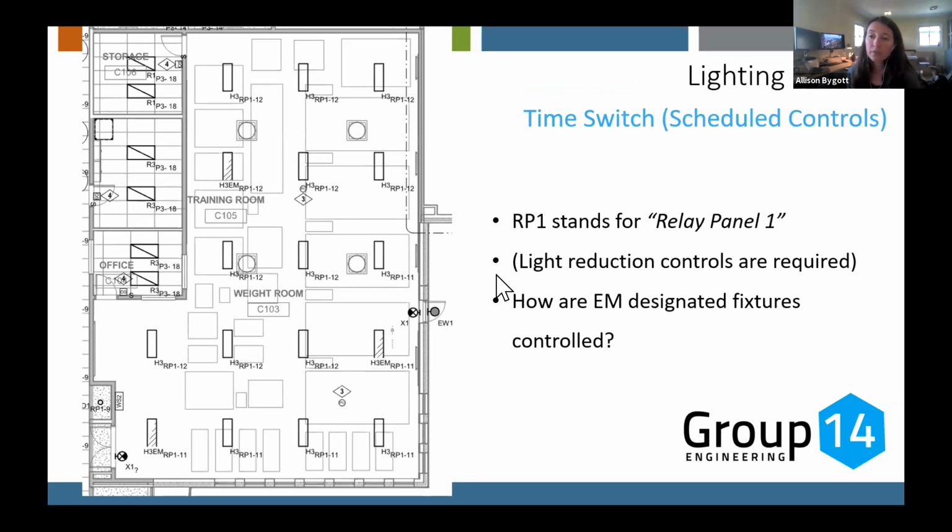One thing I've really bumped into is the IECC functional testing of lighting controls does not ask me to review emergency lighting, but we have a huge interface with emergency lighting. It's so important that we get that right. I come out and commission the lighting control system, but I don't get an opportunity to see how emergency lighting testing went. So I'm hoping that was reviewed correctly and that whoever looked at emergency lighting understood how the lighting control system interfaced with it. In this type of design that we're looking at right here, this room is on a relay panel.